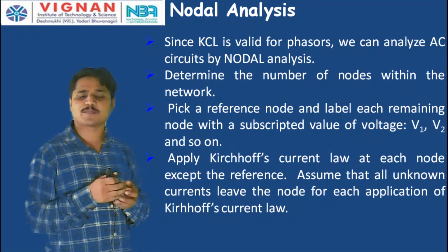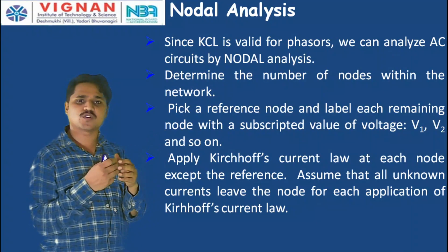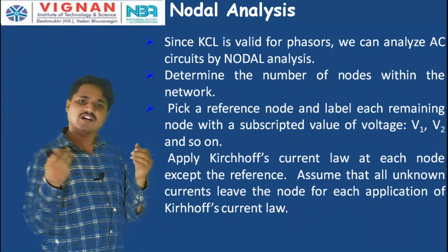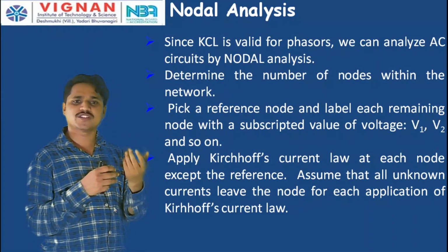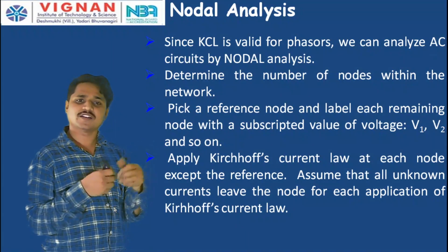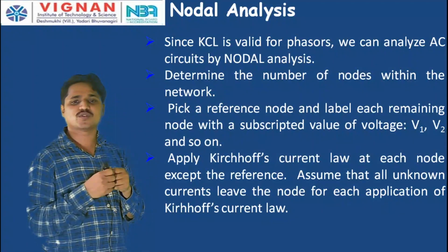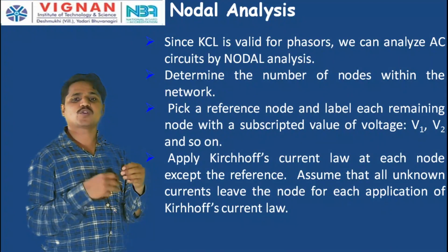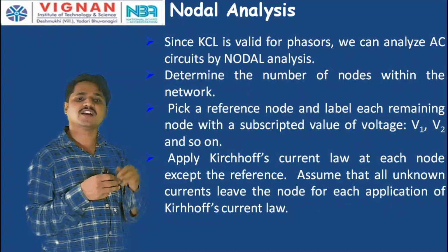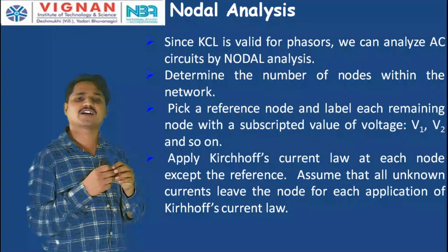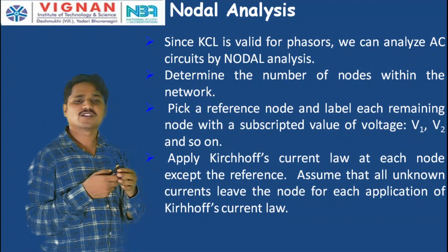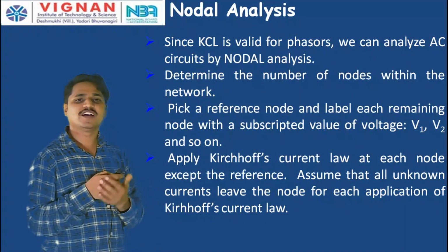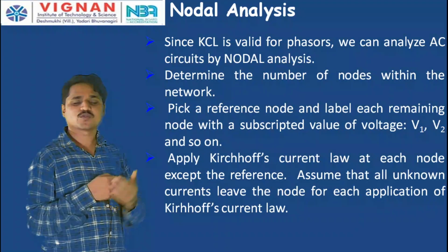See how we can apply it anyway. Entering currents is equal to leaving currents, or the sum of the currents entering any node is equal to 0, or the algebraic sum of the currents leaving the node is equal to 0. But especially in nodal analysis, it is very practically used. So, we assume that all the unknown currents are leaving the junction, and the sum of the leaving currents is equal to 0. These are the steps to follow to solve any problem by using the nodal analysis technique.